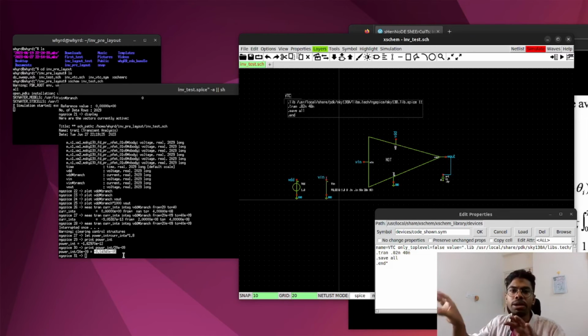So if we can compare both of these two, we can know through which architecture there is more switching activity. If an architecture or a design perspective gives you less switching activity to get the desired result, then we can use that to save our power, because we are getting the same answer with less switching activity, with less Boolean algebra in a rough sense, or less complex Boolean algebra.